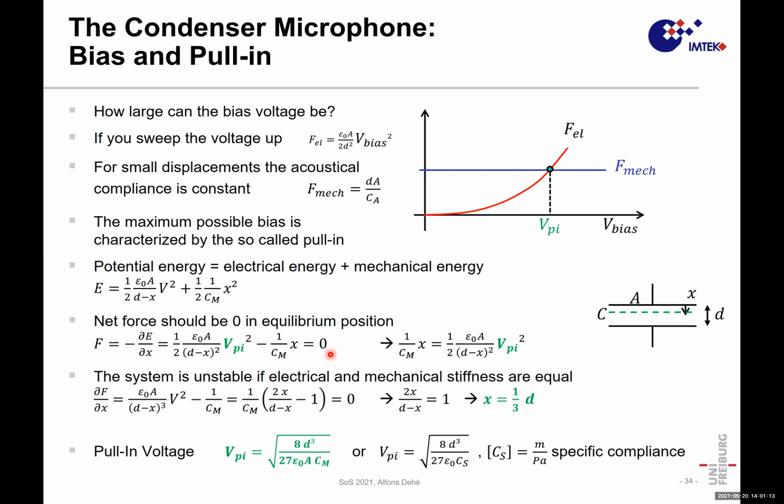And this basically gets us the critical pull-in voltage at the point where the system is collapsing. And from there, we get an indication for the displacement at the point of pull-in. We put this again into the formula. The change of force over x we can set to 0. This is exactly the point where we have this equal point, and we get out the displacement is 1/3 of the gap that we have.